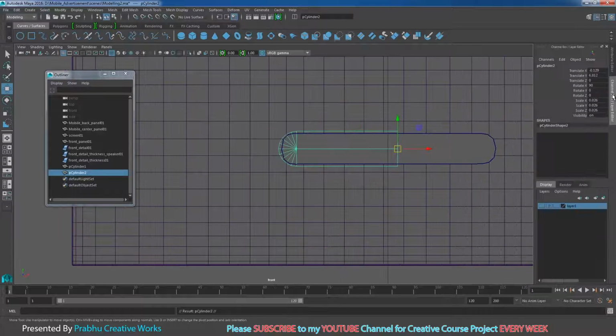So now go to channel box and layer editor. You want to scale X. So you want to give a minus value. Don't change any values over here. You will just add minus over here and press enter. So that means you got two objects over here.